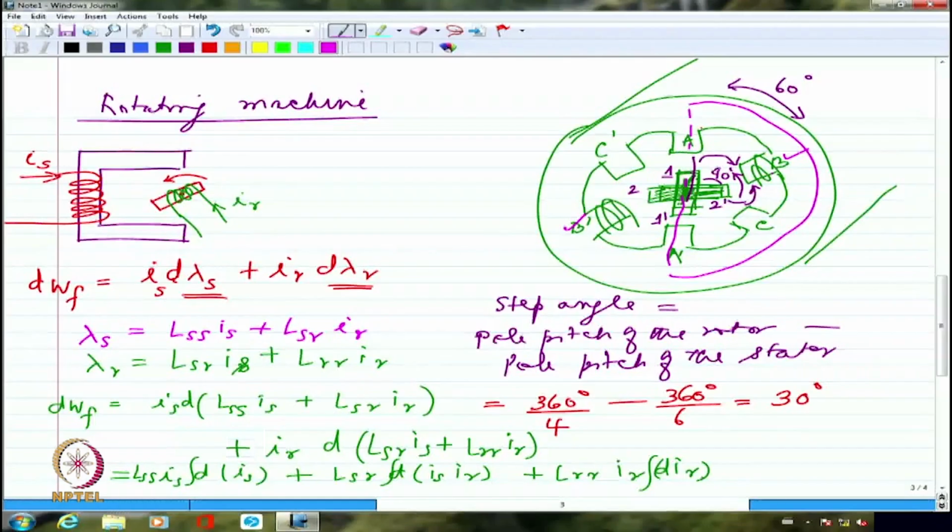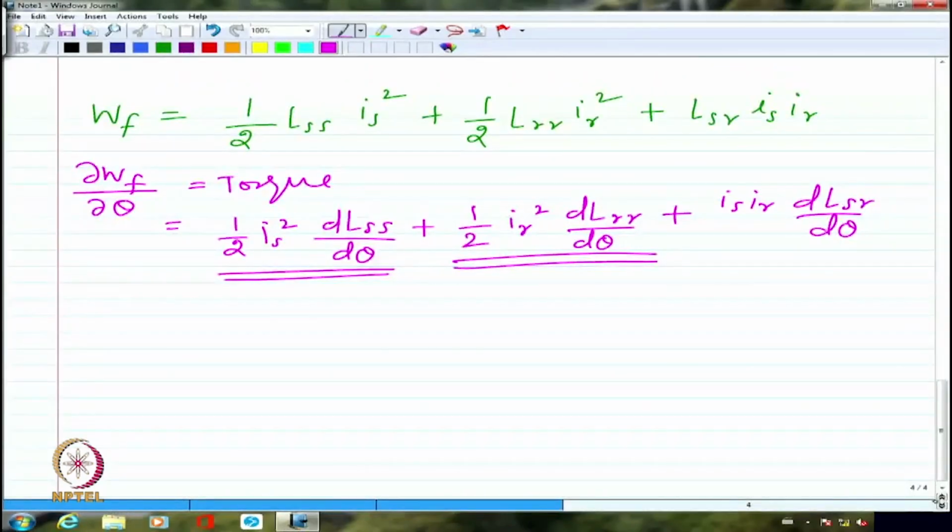So you are going to have a variation in the stator coil inductance. Even though the rotor is really not having any coil, in this case the self-inductance variation is the one which is actually creating the torque, because the rotor current is not even there. So if I try to look at the expression now what we got, this is due to stator self-inductance variation.